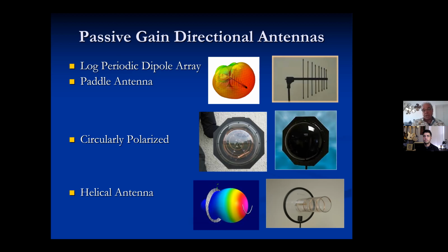Incidentally, I should mention, and the guys and gals who work shows with me see me do this, if you have a very wide stage and there's a lot of lighting or some scenic that will block RF from backstage, you could absolutely put an array of those CP antennas, the middle ones, or helicals, under the stage on a drum kickstand pointing up. I usually put them upstage, below the stage, so they're under the scenic metallic or lighting walls that are going to create your problem. And I point them out so that they're covering the stage and the artist can still go out into the audience and have coverage. In fact, usually the coverage is better at the back of the house than it is on stage because of the interference from the light walls.